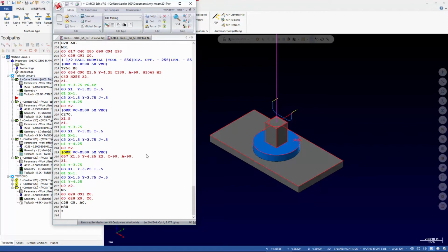Nick's got a question. Why would you want to reduce it if it is infinite? Because sometimes, even though the C-axis is infinite, its display will only display 0 to 360. If that is the case, when you cross over 360, it just goes back to 0. So it's just better to see that in the code, because then you don't have to do the math and say, oh, it's 13,284 degrees on my C-axis, but really that's 224 on the display, or whatever.